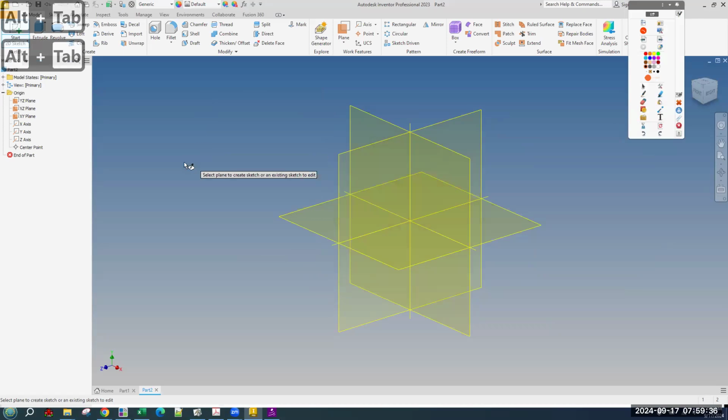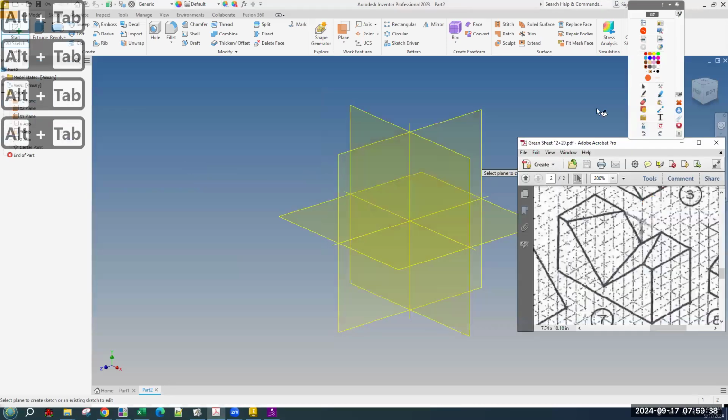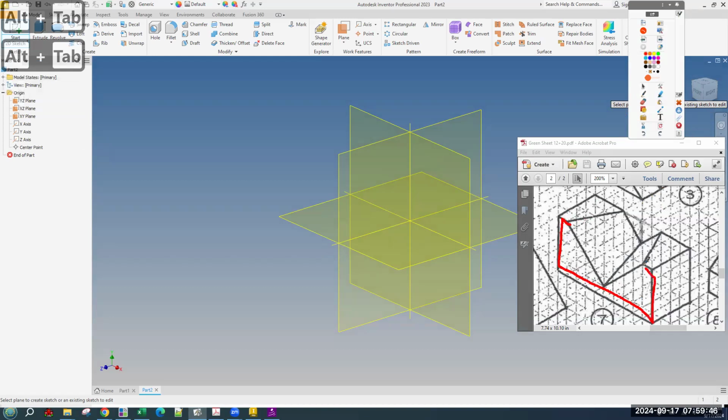Okay, so looking at part 7, the way we're actually going to do this is we're going to make 2 sketches like I showed in the example. One of them is going to be the front, which looks a lot like part J. It's just a sketch with lines. And then we're going to make a new work plane that is 4 inches behind it.